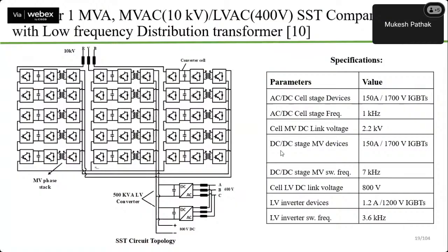And we can also form a three-phase system by using such modular systems. You can see this is one module comprising one converter on the input side, a second converter for DC-DC, and then the isolation transformer. You can connect these converters on the output side in parallel, input side in series, and then form star and delta connections also. For example, here